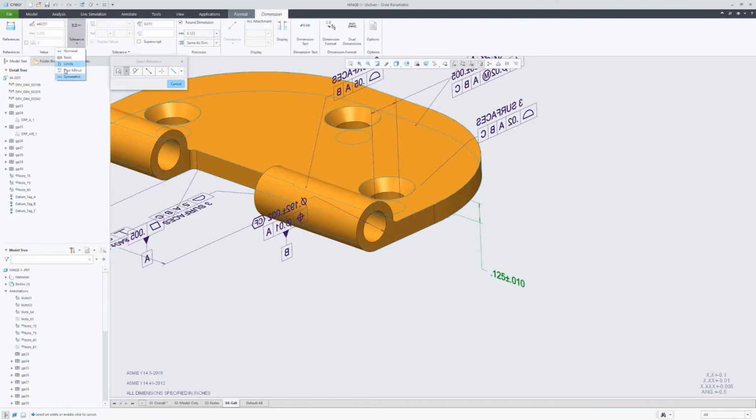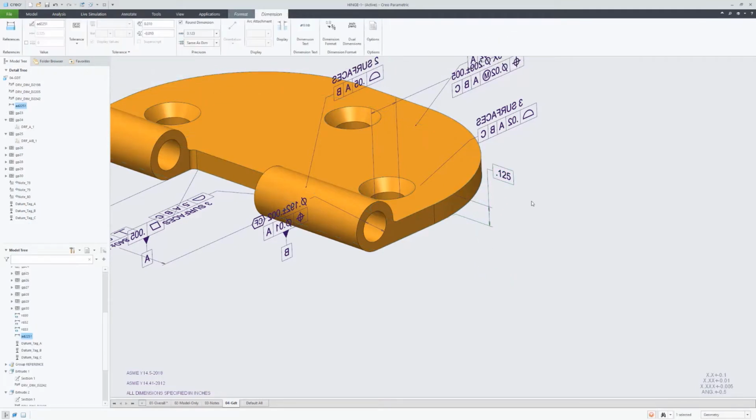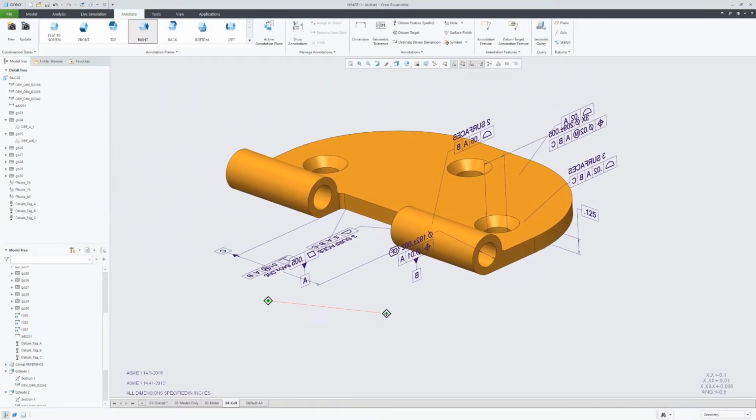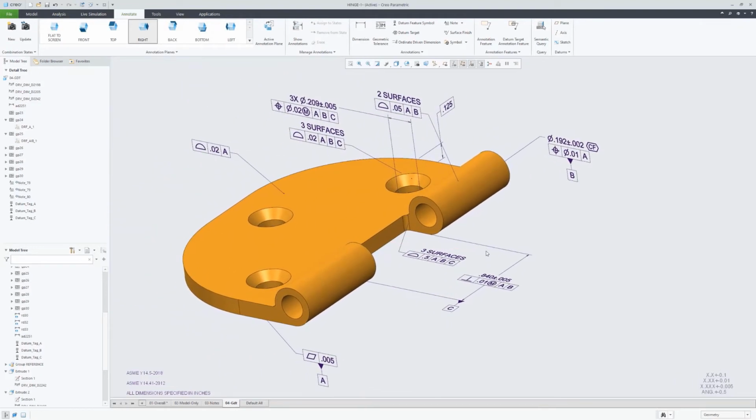So while that's being finished, I just want to summarize, right? GD&T Advisor was able to be used to select the features that the desire was to establish them as datum features, provided some advice, hence the GD&T Advisor name, of how to qualify those features. As the datum features were qualified, it was just creating those datum reference frames that could be used for other geometric tolerances. And then the same workflow approaches, you could select the features and it would add the necessary geometric tolerances as well as any size dimensions necessary to fully define those features. Thank you, and I hope you enjoyed the demo.